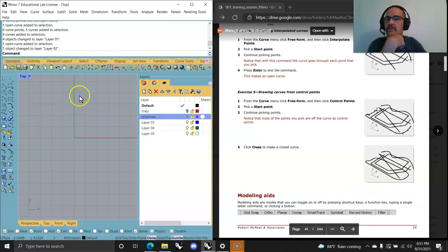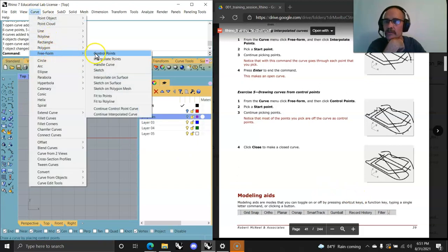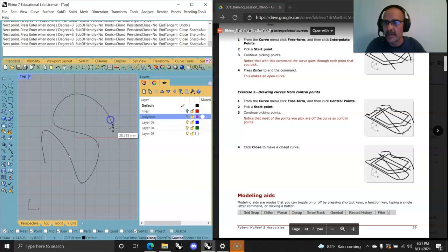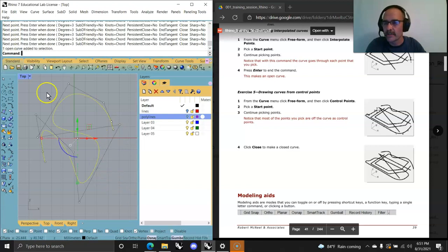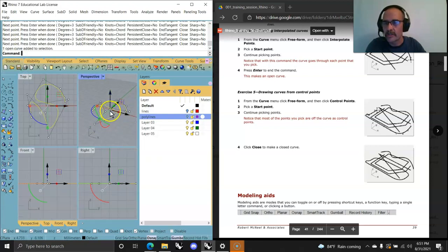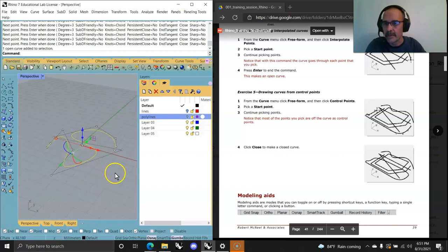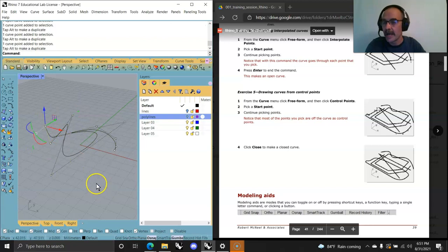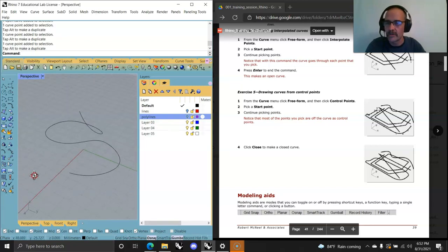As it goes through, it says there's also some other wonderful freeform curves to apply, control points and interpolate points. And I like interpolate points because I can just blast out a bunch of points like that and close it off, and I have a really nice curve that has control points on it. And those control points don't have to stay planar. I can go in and say, okay, control points are on. What happens when I start to move that line up, which was controlling that point, this point? And you realize that it is an incredible line-based editing tool, but also a surface-based editing tool.